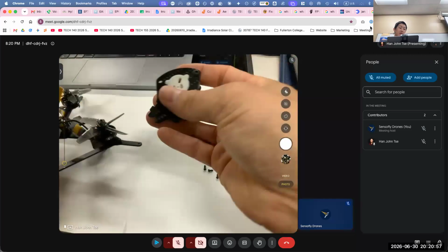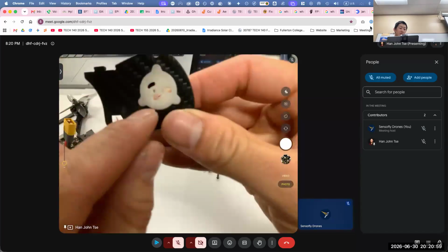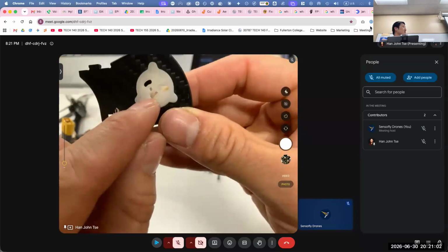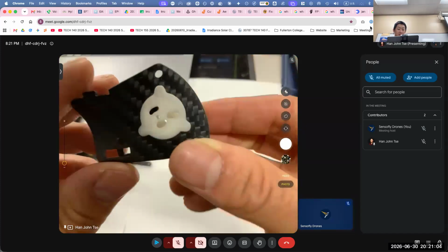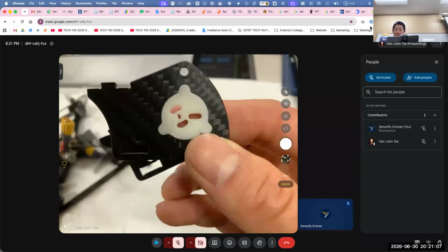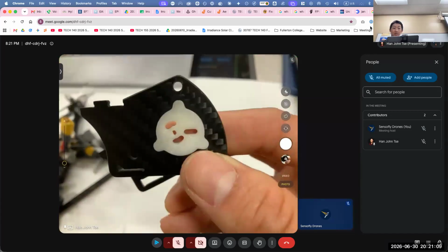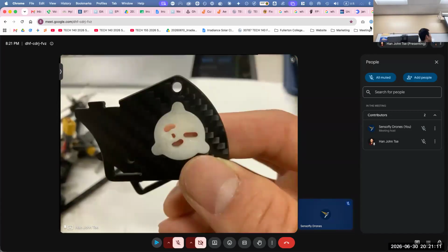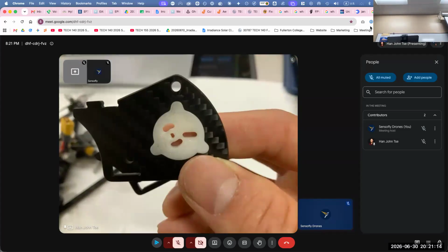And in order to tilt that, we have these little curved slots. Let me take a photo just to show you, that way it's not so shaky. What you want is the curves to be tilted this way, so the camera is gonna look that way. That's the whole point. The camera looks up to compensate for your drone tilting down, and therefore it ends up looking forward.